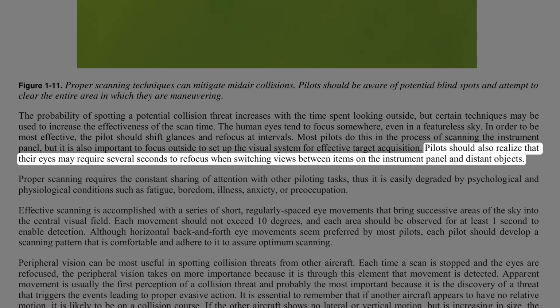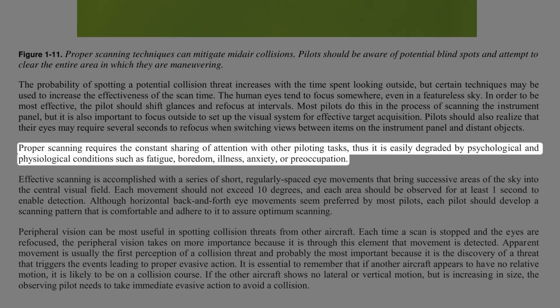Pilots should also realize that their eyes may require several seconds to refocus when switching views between items on the instrument panel and distant objects. Proper scanning requires the constant sharing of attention with other piloting tasks. Thus, it is easily degraded by psychological and physiological conditions such as fatigue, boredom, illness, anxiety, or preoccupation.